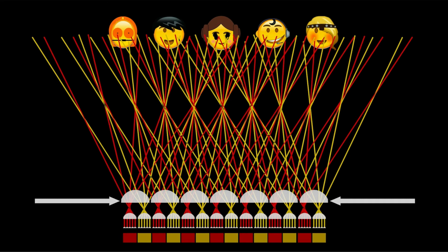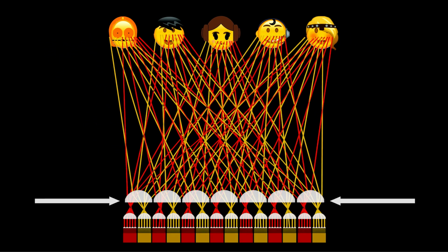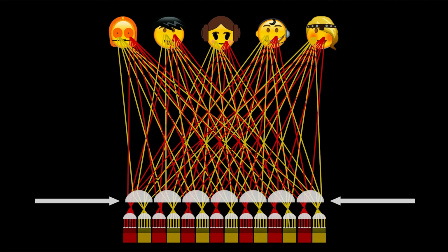For an observer to see a single image, the lights from all the pixels need to be focused on the correct viewing positions. To do so, we need to slightly shorten the width of the third lenticular layer relative to the width of the pixel layer. Each viewer now can see a complete 3D picture.